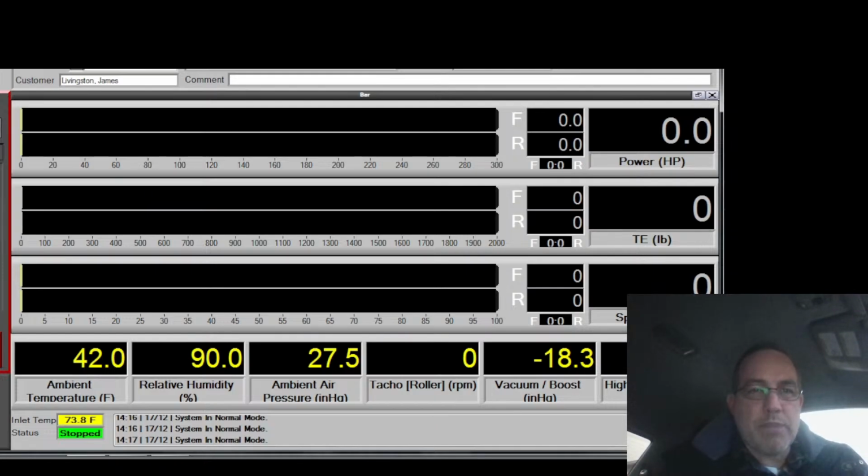And without the proper instrumentation, and trust me, we do not have the proper instrumentation here, I don't have in-cylinder or per-cylinder AFRs or that kind of stuff, it is hard to do, let me tell you. So I'm going to just add a little bit of fuel to idle, and that'll help alleviate some of those conditions.